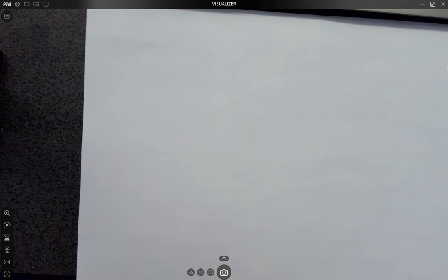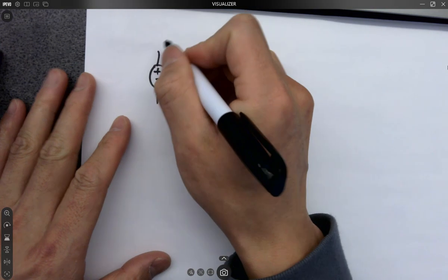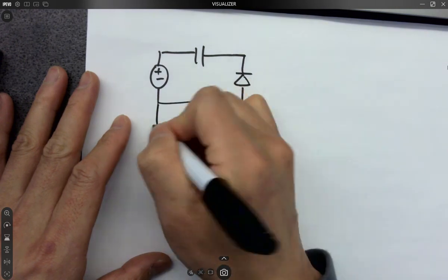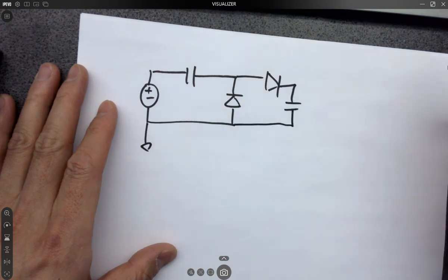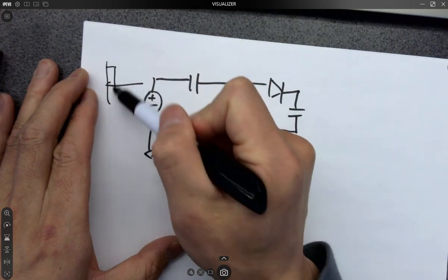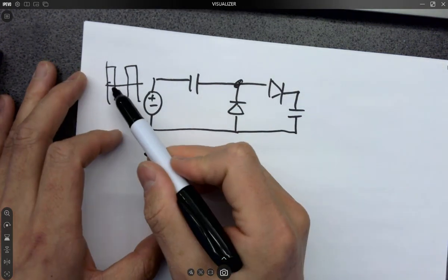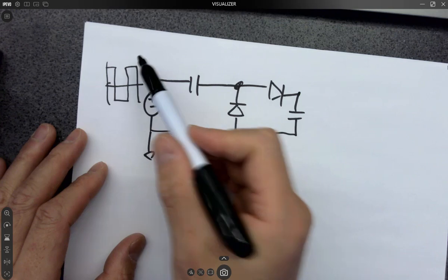So for today's quiz, it will be a really simple circuit from last time. Remember a voltage doubler. You have a voltage source. It's oscillating. Got a capacitor. Then you have to filter it out. So if this is oscillating like this, this point is going to lift this voltage up by 50% of the amplitude, and eventually this will be the DC output from that output over here.